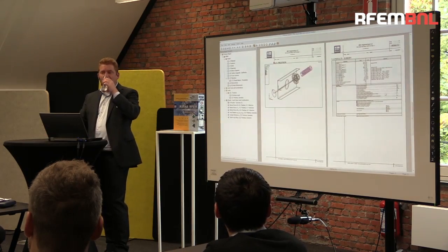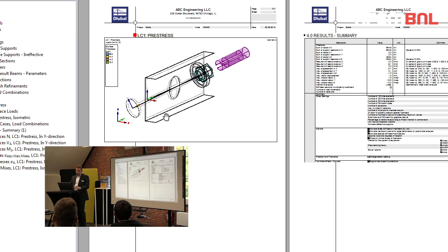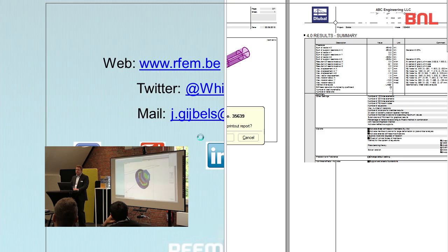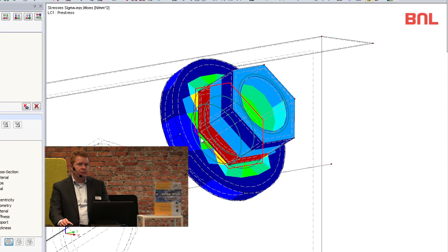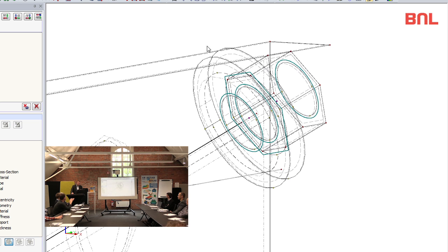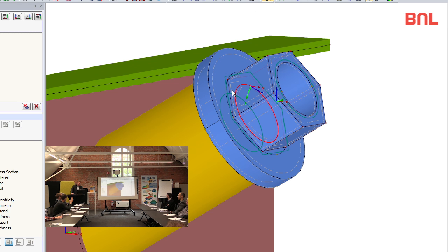It was connected to the flange, this plate, this ring. Should you not make some contact property? Yes, but maybe. You mean contact? Why? Where? Where, Peter? Where the nut touches, no, it's automatic. Yeah. If they share the same finite element nodes, the mesh generator does it.